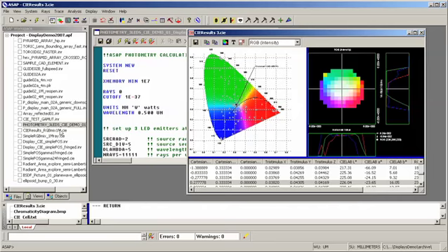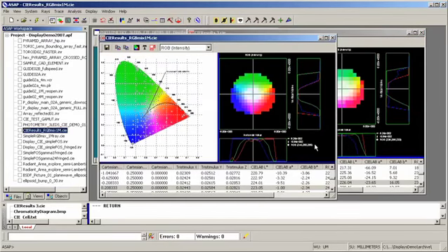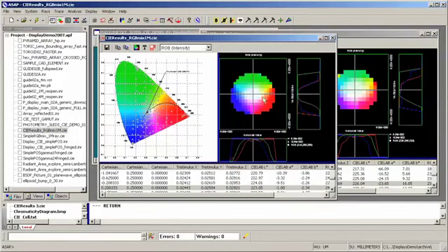Now let me open the result at somewhat higher resolution for a larger number of rays. And in this case, we will have a cleaner definition of white in the center. It's not marked, but it's somewhat improved white in the middle. And more rays always improve these results because, as with any measurement based on statistics, each ray is a statistical trial, and the more rays you have, the better.